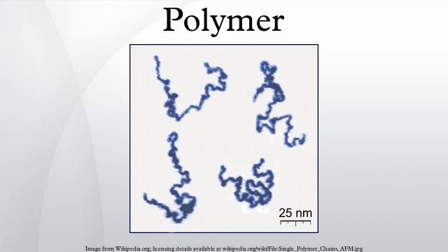Synthetic polymers may consist of both crystalline and amorphous regions. The degree of crystallinity may be expressed in terms of a weight fraction or volume fraction of crystalline material. Few synthetic polymers are entirely crystalline. The crystallinity of polymers is characterized by their degree of crystallinity, ranging from 0 for a completely non-crystalline polymer to 1 for a theoretical completely crystalline polymer.